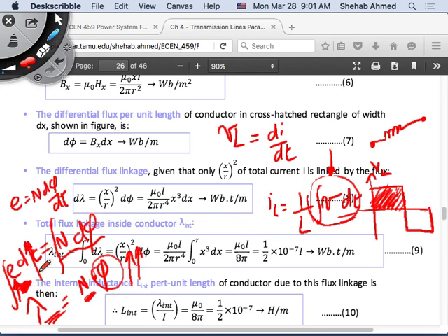And that's how you choose the core that you design. The inductor core or the transformer core is based on this limit that they will give you in the data sheet of the material. They will tell you this material has a certain flux density that you should not exceed.